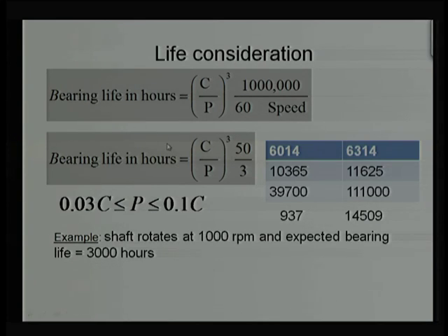So coming to the other side, the bearing needs to sustain some load. However, there will be some sort of vibration, because we know the rolling elements will have some separation from the inner ring and outer ring. There will be some clearance. If there is no load, there will be a lot of vibration, a lot of noise. That's why there is a need for some load on it.